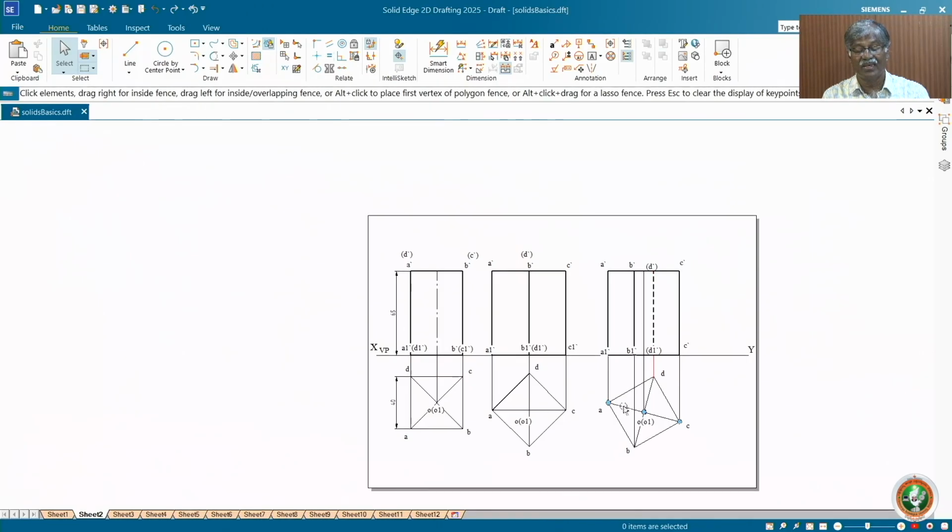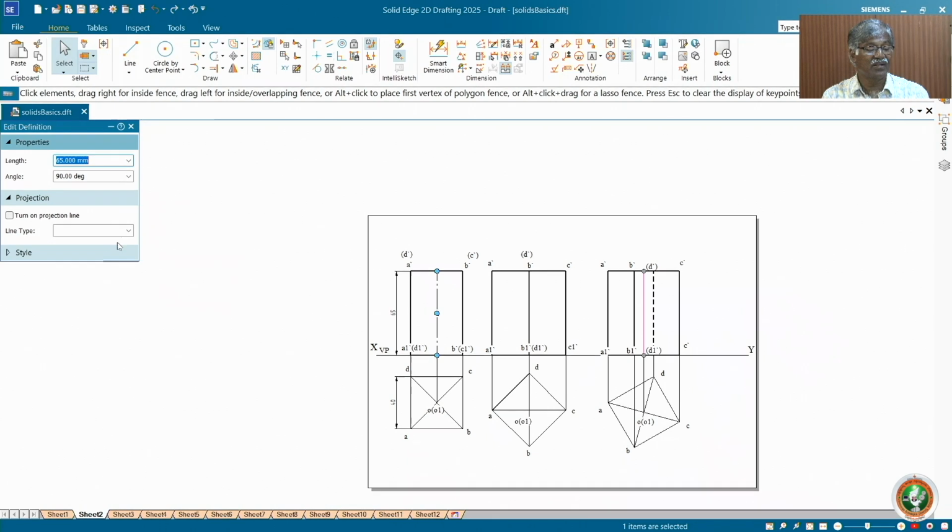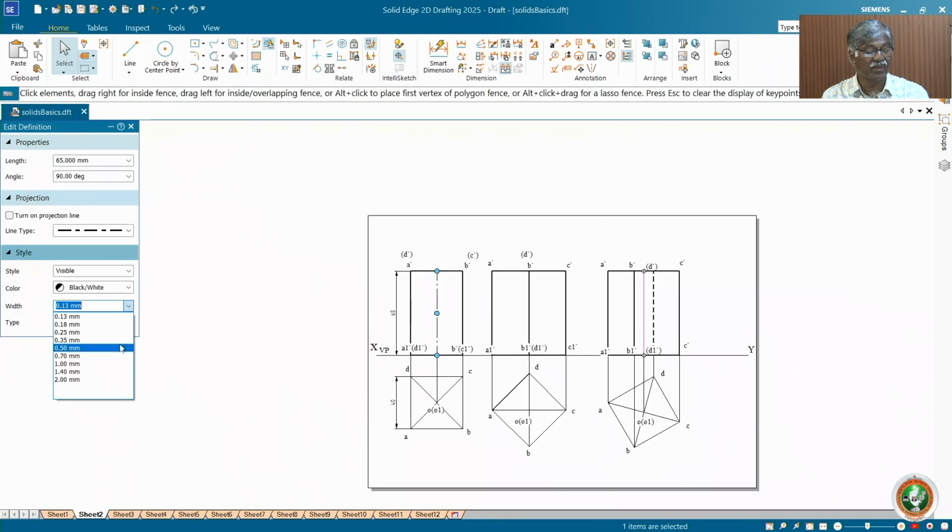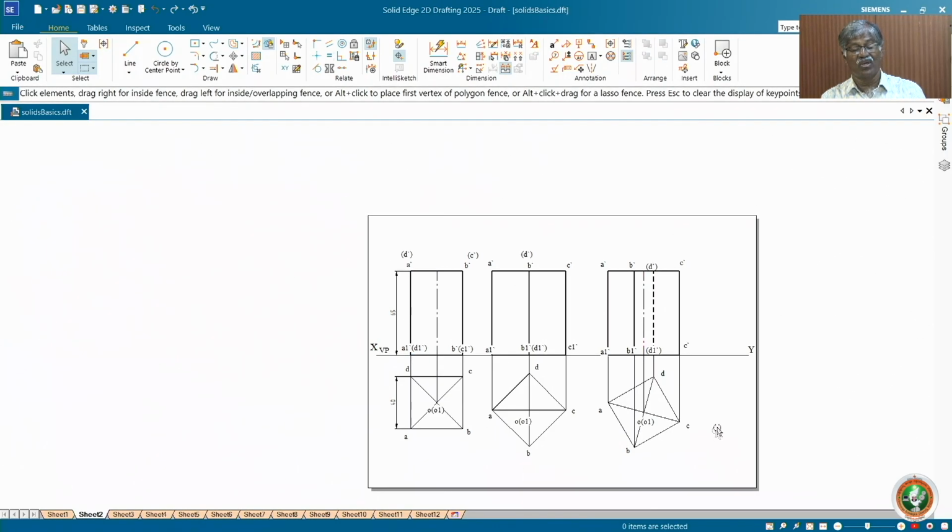So there is scope for all the types of lines here because nothing is hindering O1 from coming. So nothing is in front or behind. If you have anything in front of that, then you never get a chance to mark axis. Or even behind, a hidden edge, no chance to mark axis. Here it is free. Definitely take this axis, third one, and again do this. Okay, 0.35, because it is an imaginary one.